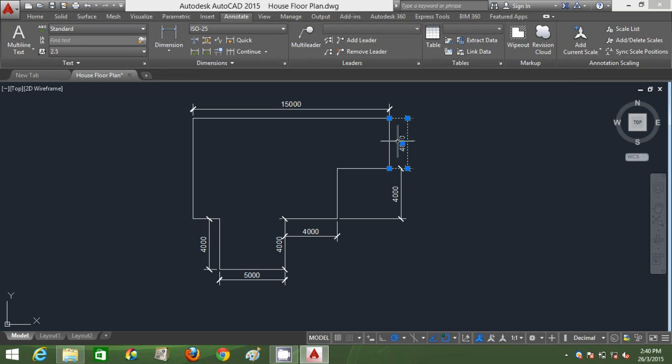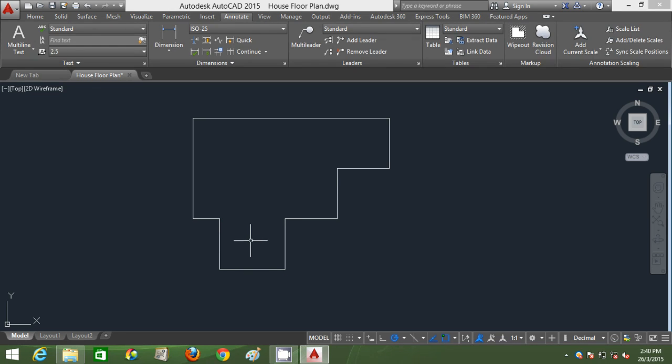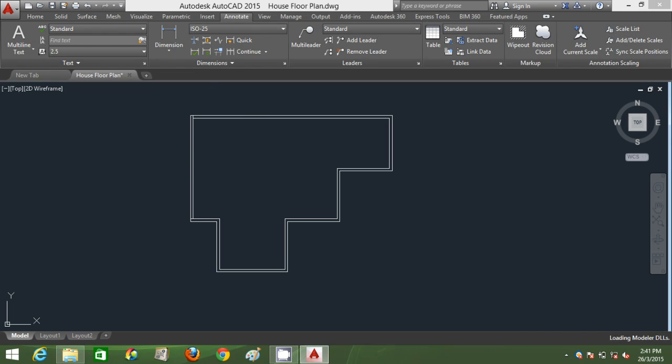So now I'm going to turn this particular floor plan into 3D structure. So I'm just going to delete all the dimensions first. I'm going to digital trace this particular floor plan, offset it to 200 mm. I'm gonna digital trace this part using a rectangle, and I'm gonna digital trace the rest and region of that.